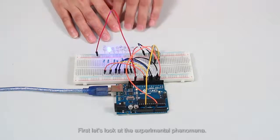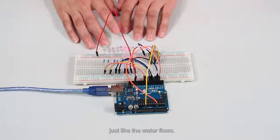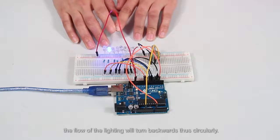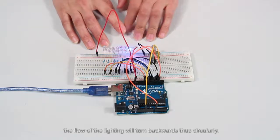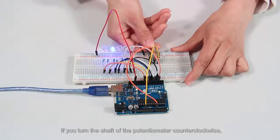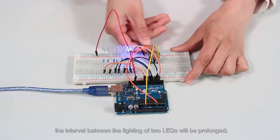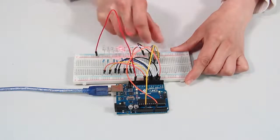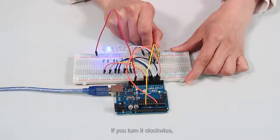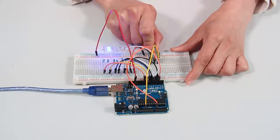First, let's look at the experimental phenomena. The LEDs will light up one by one, just like the water flows. When the last LED goes out, the flow of the lighting will turn backwards, thus circularly. If we turn the shaft of the potentiometer counterclockwise, the interval between the lighting of two LEDs will be prolonged. If we turn it clockwise, the interval will be shortened, which means the flow will speed up.